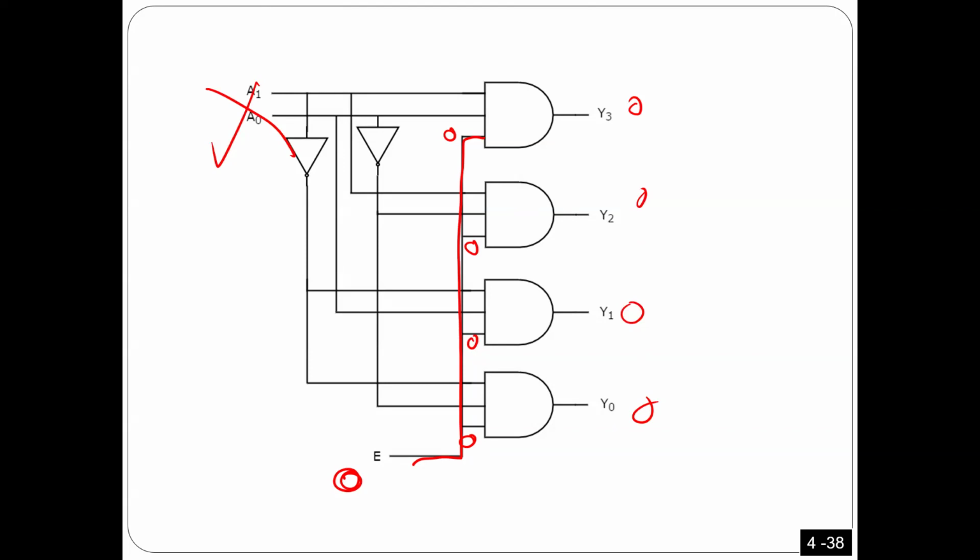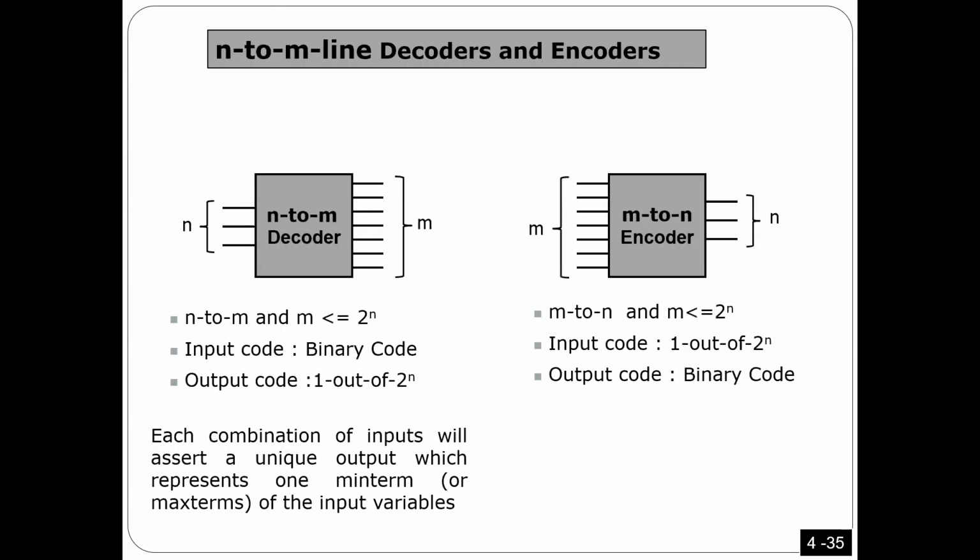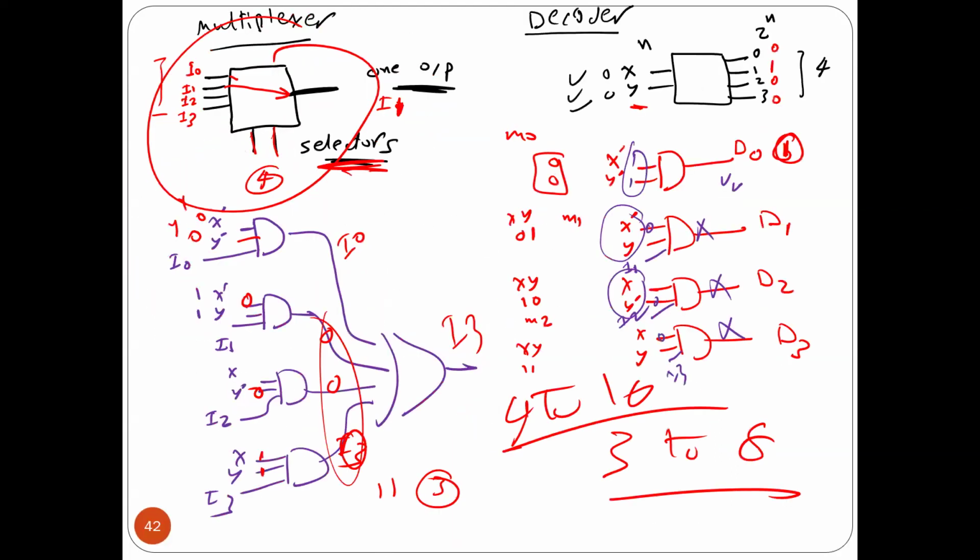So in a way, the difference between the multiplexer and decoder is that the decoder just has all of the selectors fused into one wire, using the enabler. Regarding architecture it is very close, but what each one is doing is different. This one is like a switch.